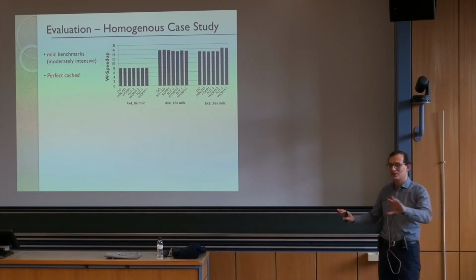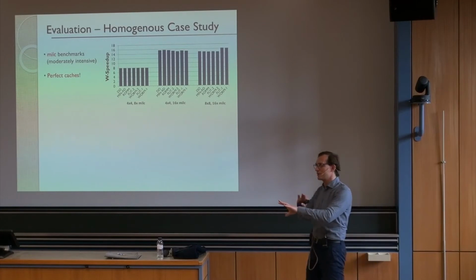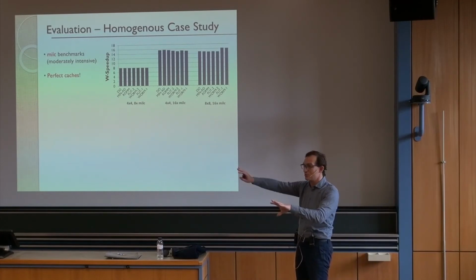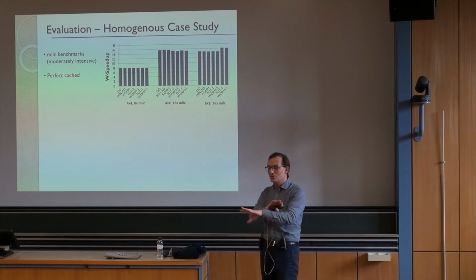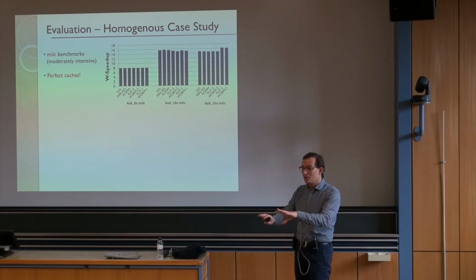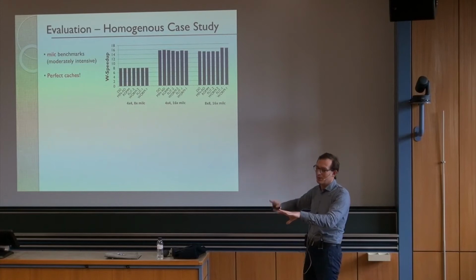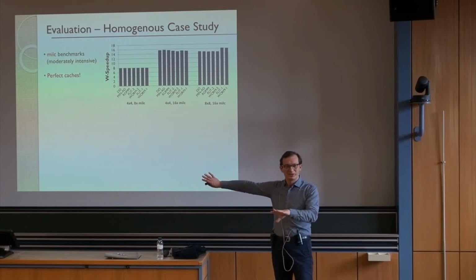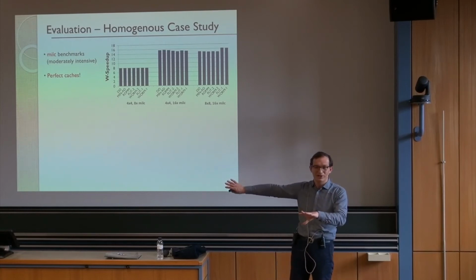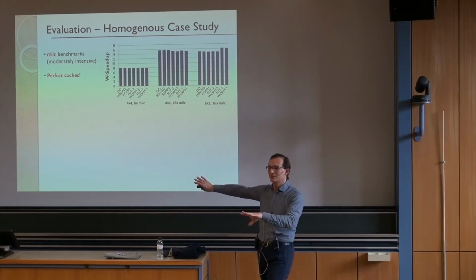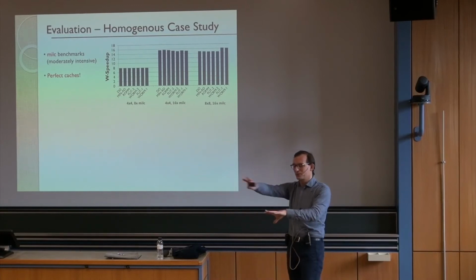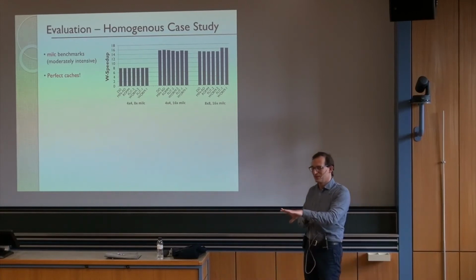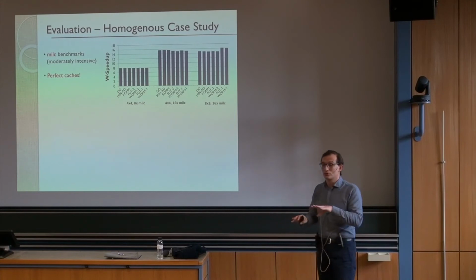Because you miss in the cache, and then you have communication between the L1 caches and the distributed L2 cache, let's say. And then sometimes you hit in the L2 cache, you get the messages back. When you miss in the L2 cache, or L3 cache, you go to the memory controller, and those flits get decommissioned for a while because now it waits for the memory latency, right? So it's out of the network that's on chip. So that's why there's not a lot of load on this network.